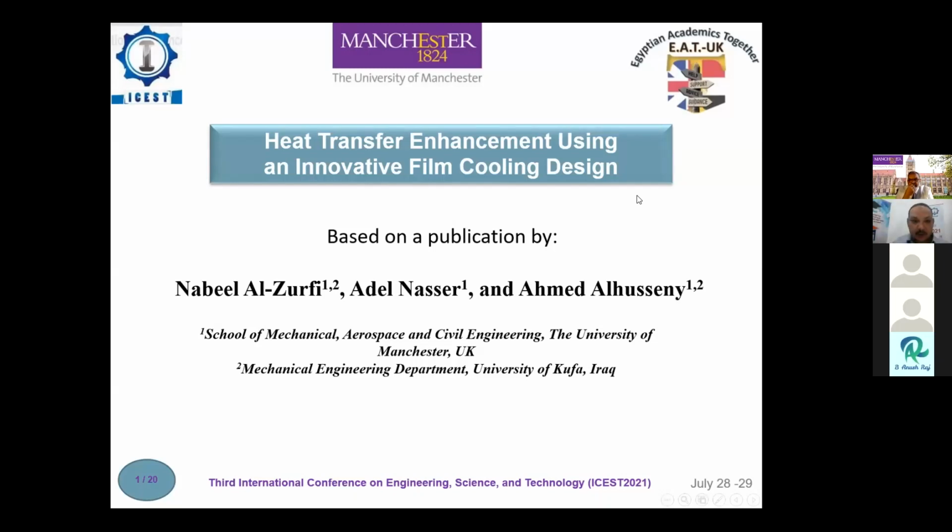Basically, our work is about film cooling in gas turbine blade. This work deals with two main parts, technical part and CFD part. In the first part, film cooling has been improved by using an innovative cooling technique. In the second part, the powerful tool, large eddy simulation, has been used to predict the film cooling performance. So, this paper also takes into account the large eddy simulation requirements such as grid size and time step.